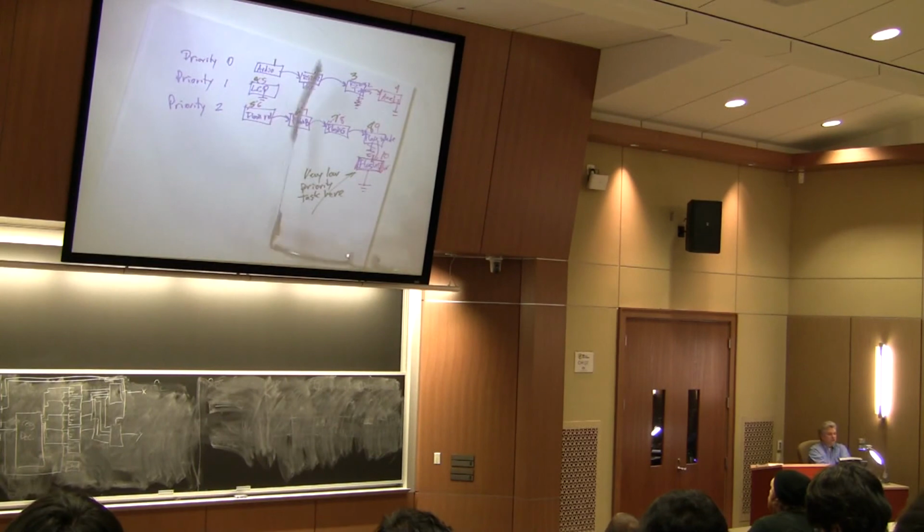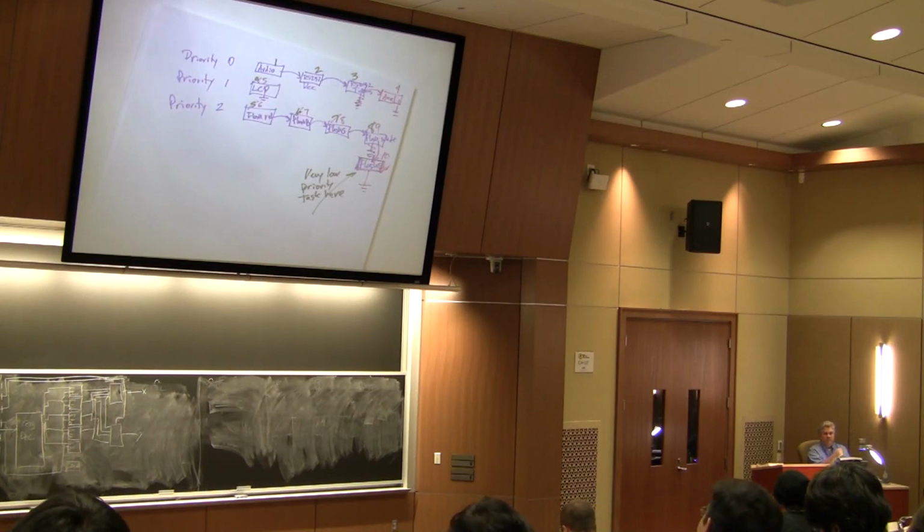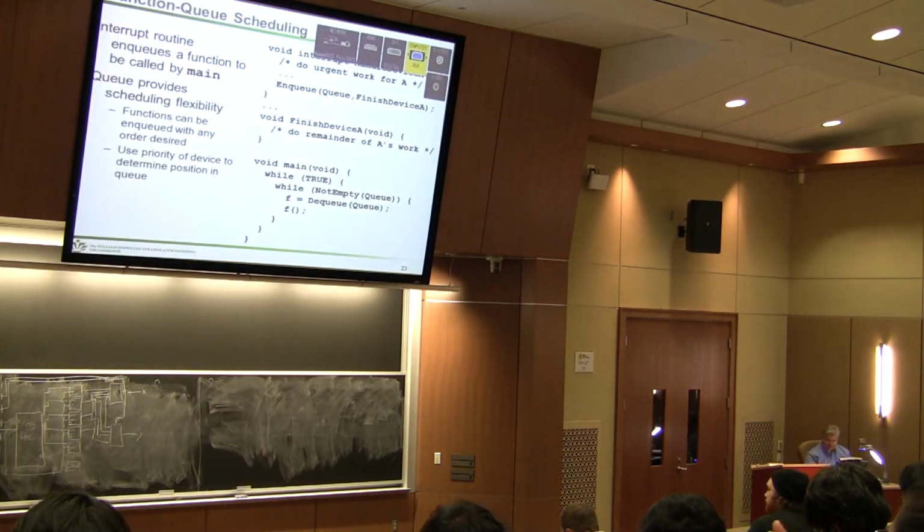So this just tells you the priority that you need to address it. Does a human need to see a flashing LED really frequently? They can't tell the difference between a 1 millisecond flash and a 10 millisecond flash. However, if you don't handle the audio quickly, you may lose that data. And so that's why you would do a priority scheme like that.